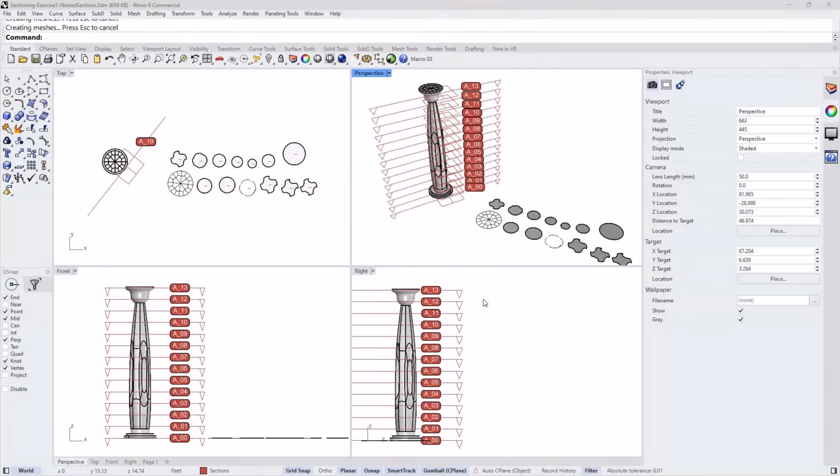When I just ran the array here, it gave me them all being the C0 instead of the different labels. Yeah, as I said in the beginning, this has been created with a clipping plane, which is not registered with the list of sections. So I said just delete the C0, and we recreated that clipping plane using the clipping section command. And if you do that and array it, it's going to give you unique labeling.